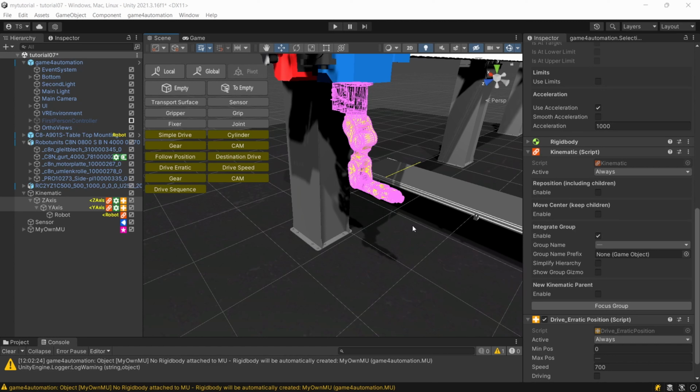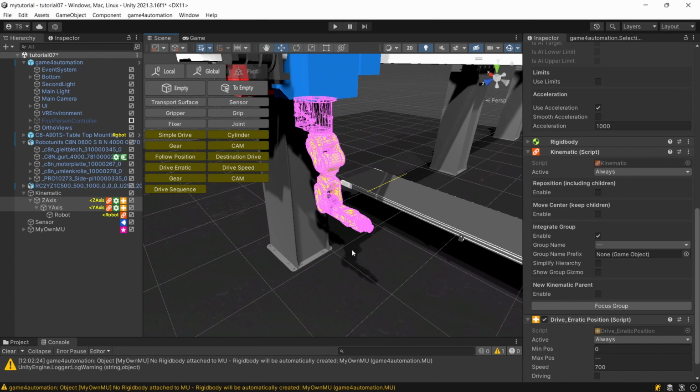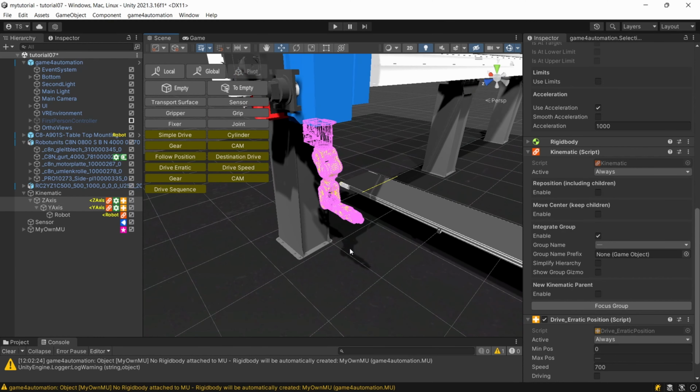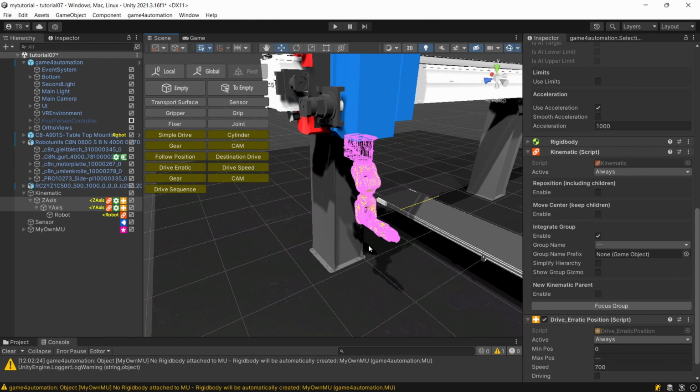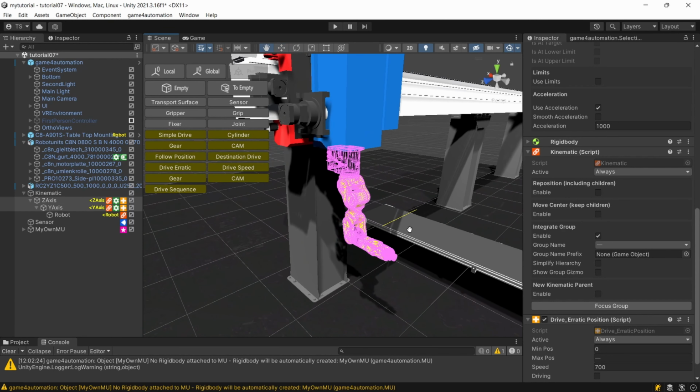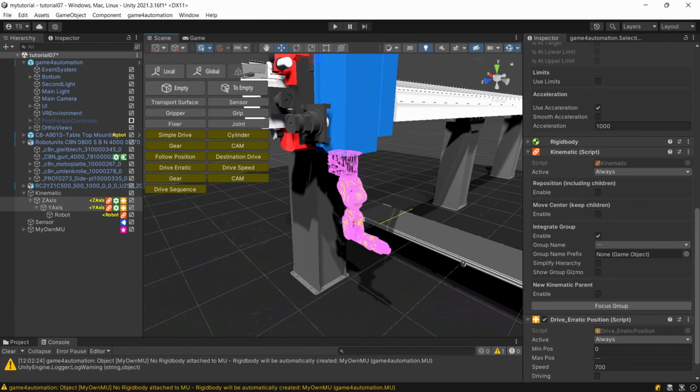First of all, I'm going to show you how to define simple logics without the need of programming real PLC code on the PLC itself, or without the need of really writing C# .NET code within Unity. The simple logics, we have implemented them as so-called logic steps. They do not replace real programming, but for simple things, it's a fast and easy way for developing your own functions.